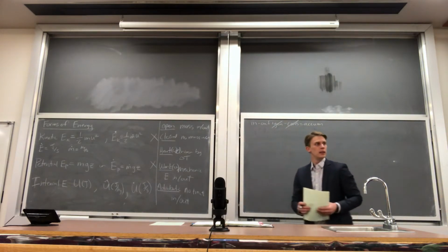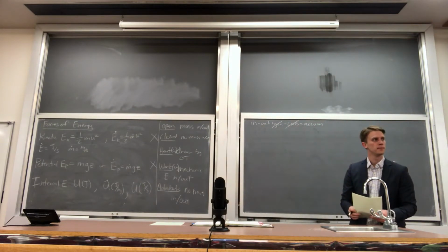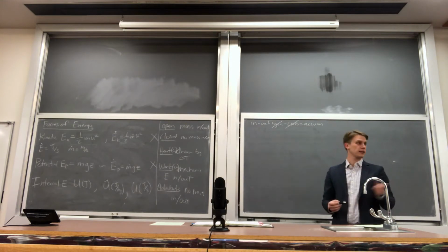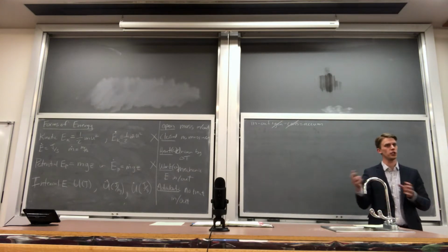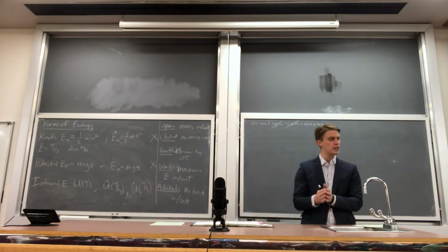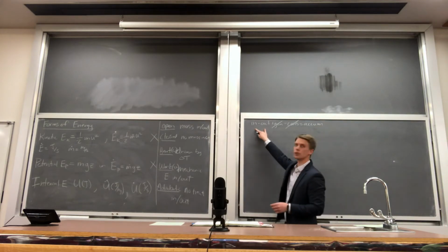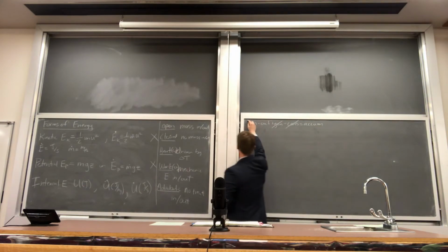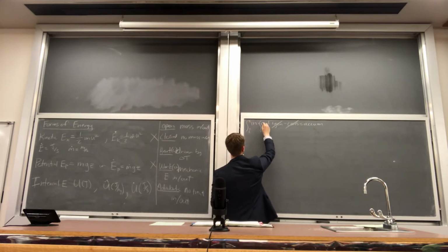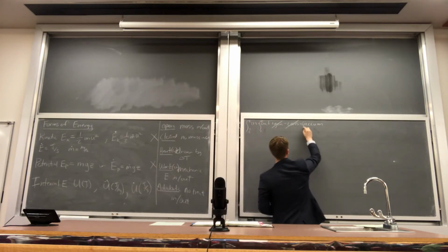If it were a closed system, though, wouldn't the accumulation just be like the change that has occurred in energy? Yes. So in a closed system, the change would be over a period of time. So for closed systems, we often use the integral form of the balance equation, where we integrate these over some period of time, going from some initial state to some final state.